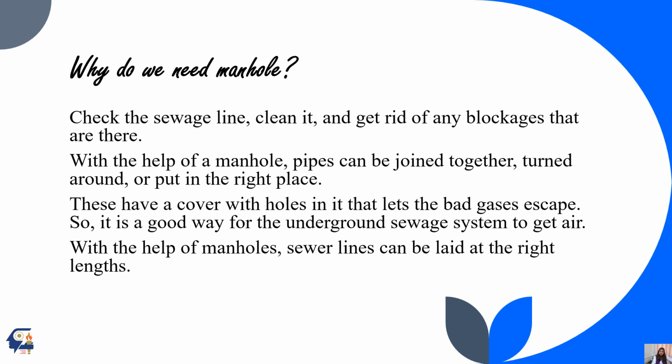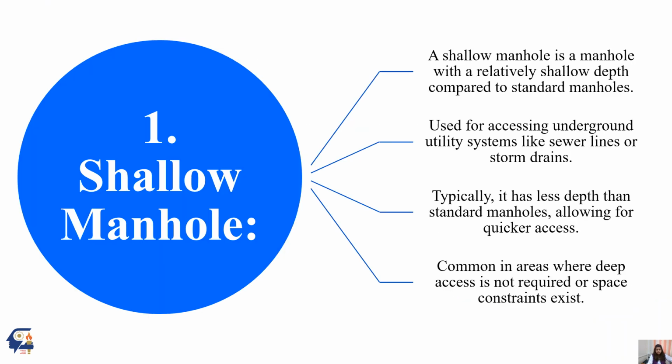So sometimes these covers with holes also help us to escape certain bad gases that have been produced because of the sewage. And with the help of manholes, the sewer lines can be laid at the right length. So that's why it is very much needed to construct a manhole. There are types of manholes.